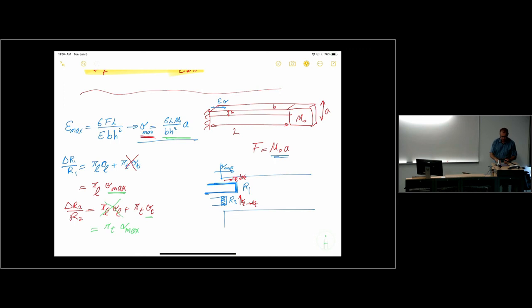But anyway, you can calculate M from the dimensions of the proof mass and density of the material that is given. And pi L and pi T are also given, and sigma max you can calculate from dimensions of the cantilever and the value of the proof mass, and normalize it by A to get sensitivity. Okay? And I will calculate these numbers and provide them to you during the live lectures if you want to check the final values with me.